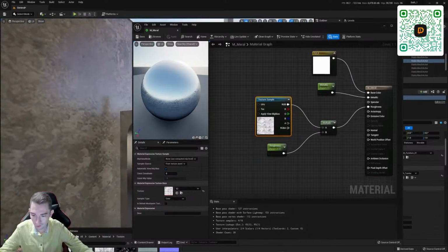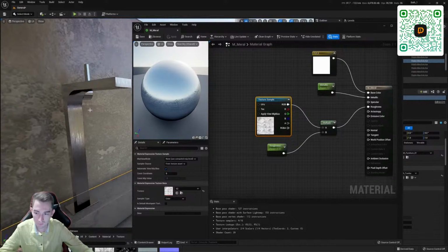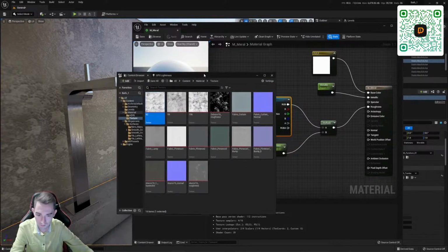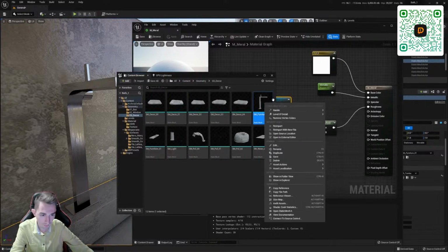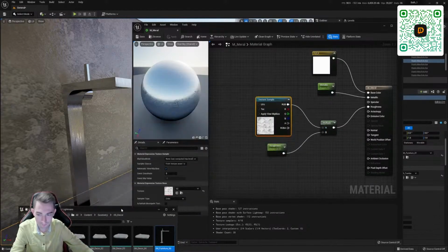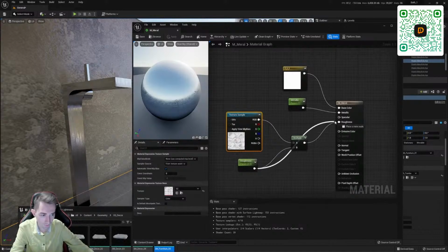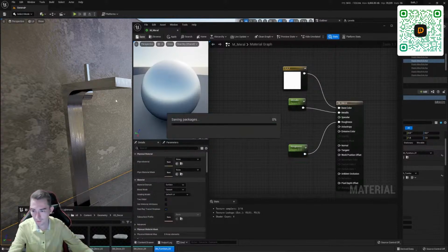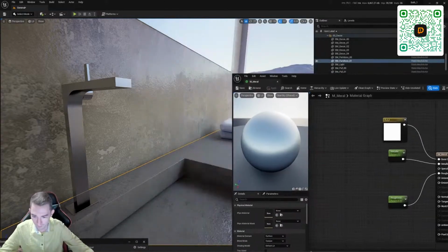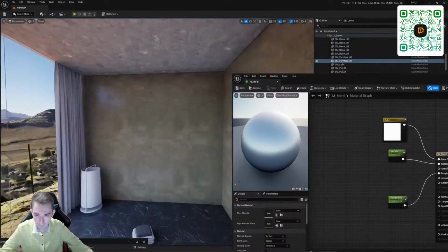That is, in a good way, you need to go to 3D Max, assign a UVW map in the form of boxing, and re-import to Unreal. You can import it like this. We go to Geometry Decor. Let's say we remove the faucet, right-click, and do a re-import here. In other words, we changed the FBX object and imported it. Now I won't use the material, I'll just do a roughness like this, as I did before.